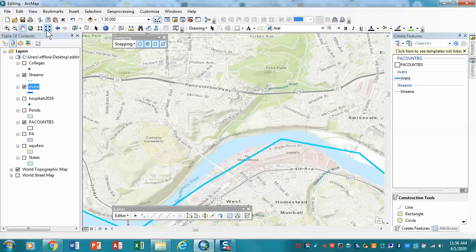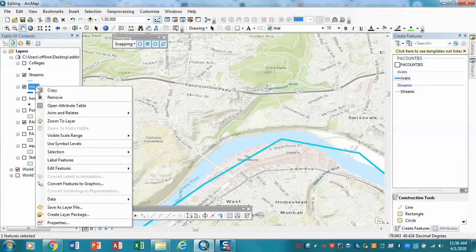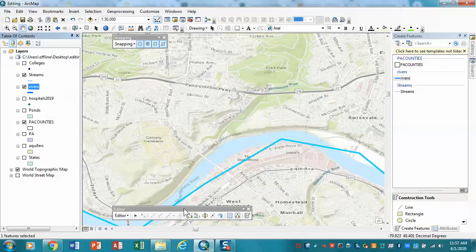And so if you follow the waterfront down, you'll see here is 9 Mile Creek. This is what we're interested in digitizing. Now, a couple of things that I'm going to do real quick to make my life a little bit easier. My rivers, I'm going to open that up, and again, it's already in editor mode. I want to move it a little bit closer to this, so I'm going to double click, expose my vertices. I'm going to add one here, and I'm going to bring this up so that this will work a little bit easier.